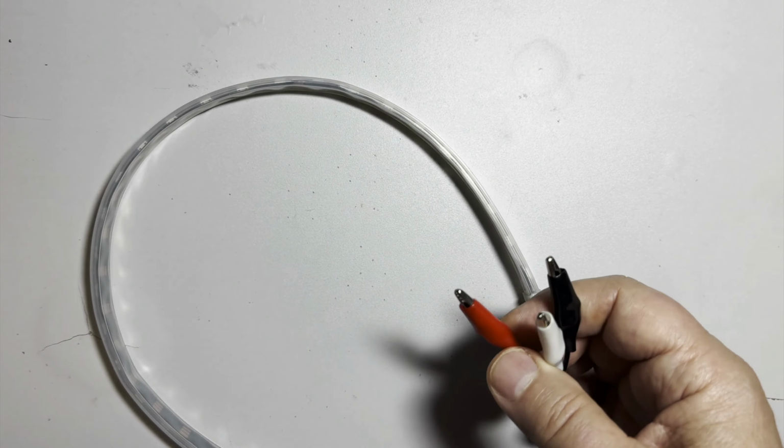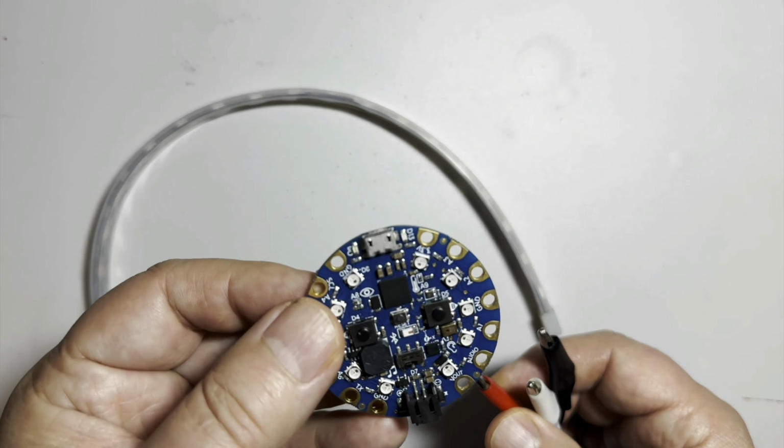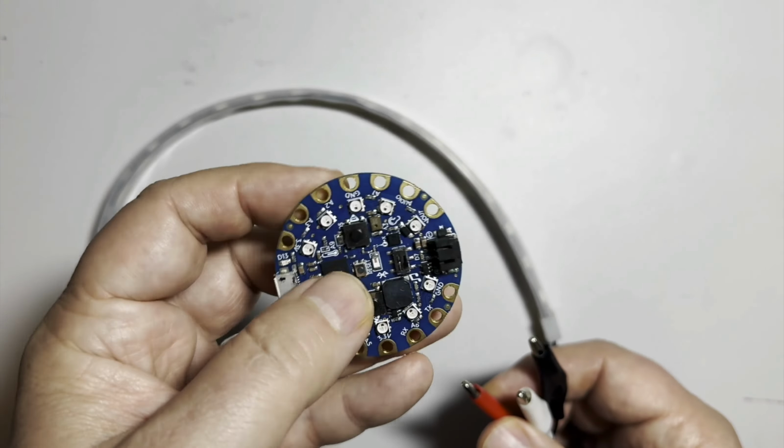Now, this is how we attach the strip to our CircuitPlayground board. First, make sure the board is unplugged. You probably won't run into a problem if you plug and unplug the strip with the board powered up, but sometimes you can cause a short, and in the most extreme cases, you can wipe out files on your board and you'll have to do a reinstall.